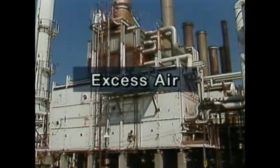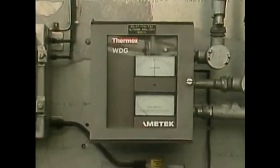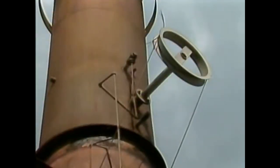Now, excess air readings are based on analysis of the flue gas. In general, this analysis determines the percentage of oxygen in the flue gas, and that percentage gives an indication of excess air. Furnaces normally have draft and excess air targets or acceptable ranges. Operating within the targets can save money in fuel costs. Basically, the airflow conditions in a furnace are controlled by coordinating the positions of the stack damper and the burner air registers.